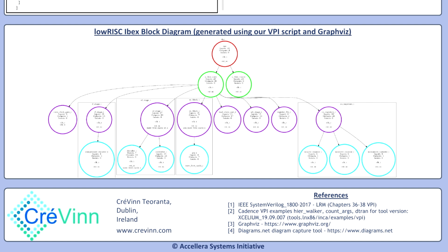One option is to highlight key blocks in the design. This is shown by placing a box around specified module groups. You can see that each module has a list of the number of inputs, outputs, and inouts to the module. Clocks and resets present are also listed. These are both configurable options.